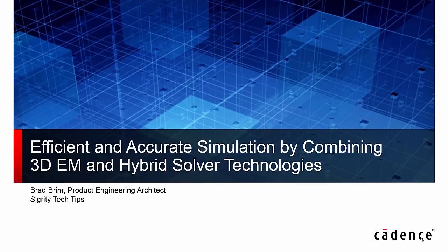Today, I will expand on a previous Sigrity tech tip by my colleague Charlie Shih on the topic of cut and stitch EM simulation flow. This flow was initially implemented as an automated approach to 3D EM simulation. I'll discuss and demo how this same flow can apply hybrid solver technology to yield essentially the same results while saving significant time, both computer time and engineering time.